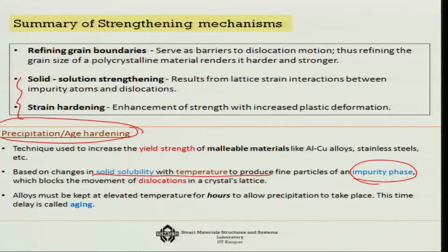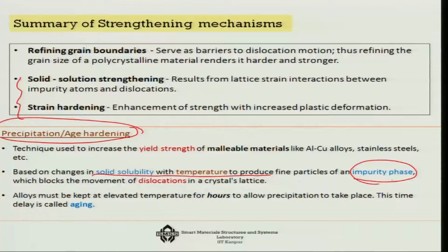So, for example, at a slightly higher temperature, you may see that there can be more impurities spread inside a pure metal, and they act like nucleation points, and then as you keep it at a very low cooling rate, gradually these impurities affect the grain formation, and as a result it affects the hardening.